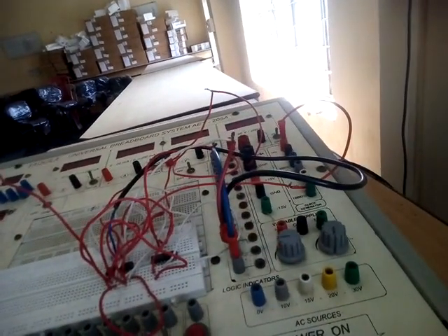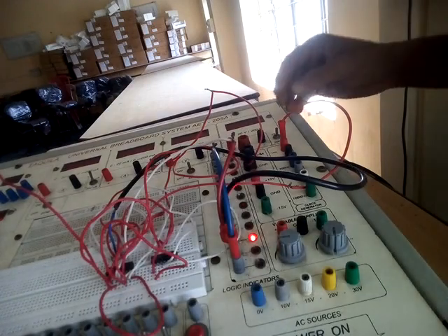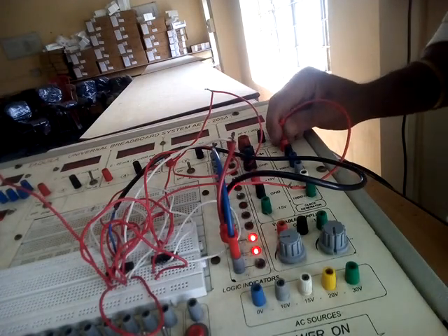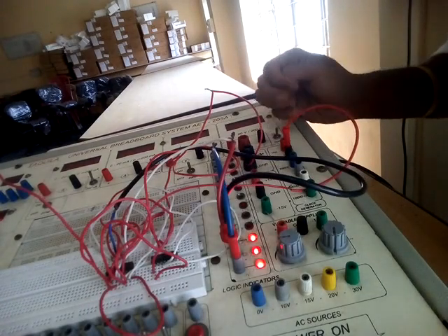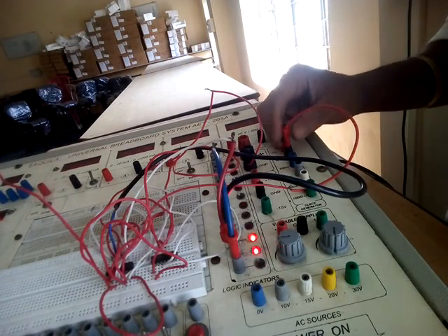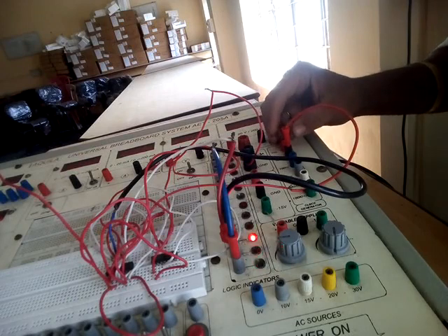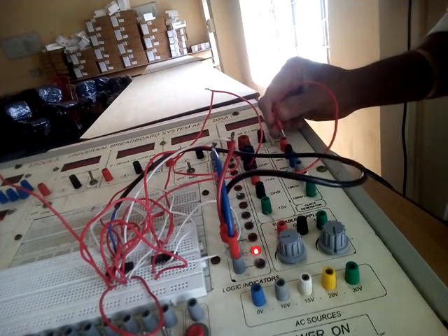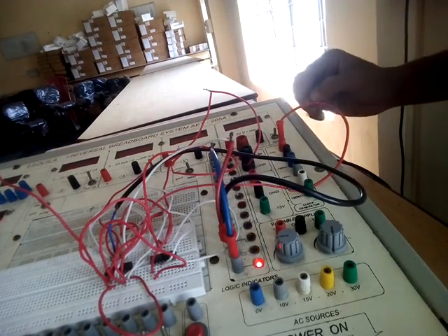You can see 001, 010, 011, 100, 101, 110, 111. If you give the clock pulse at 10 Hz, it will go faster. So the lower the frequency of the clock pulse, the more properly you can see it. So I give the clock pulse from 1 Hz.